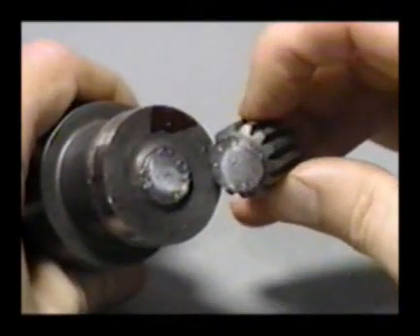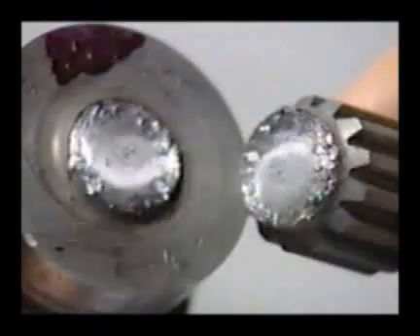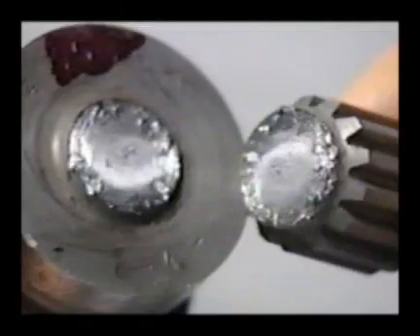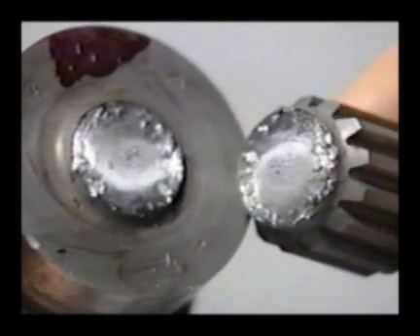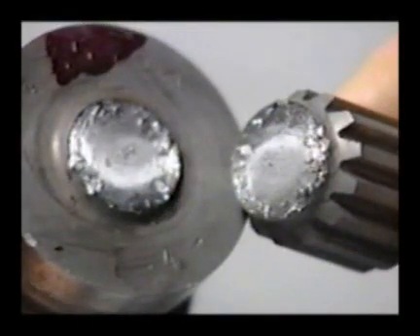Transverse shear fractures start by tearing the grains around the circumference, where shear stress is the highest. Cracks then progress inward, and final fracture is toward the center. The fracture faces usually slide against each other and smear the fracture detail.